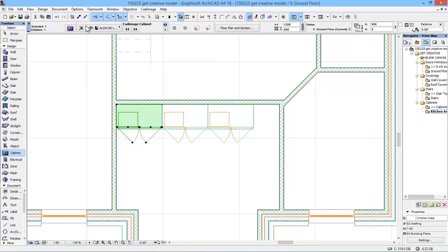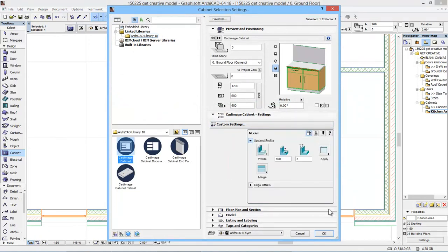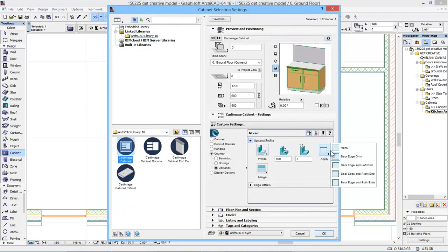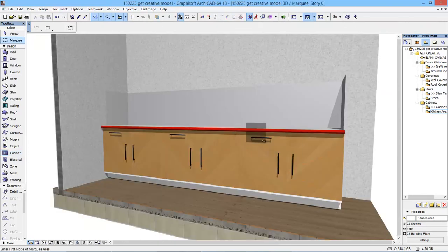And what I can do is pick up the first one, and the upstand will make back and left. And we'll pull it back 100mm from the edge. And then we'll take the last one, we'll make it back and right. And again, we'll pull that back. So if we take a look, this is what I've created, this bank of components.